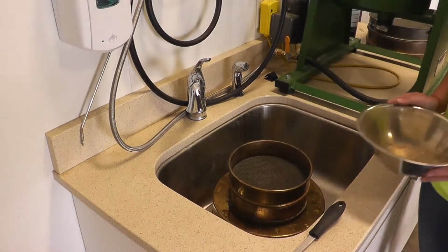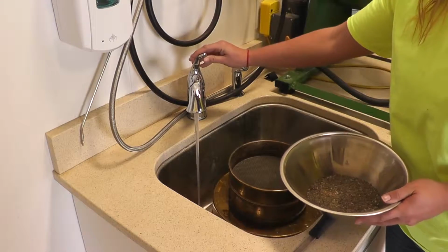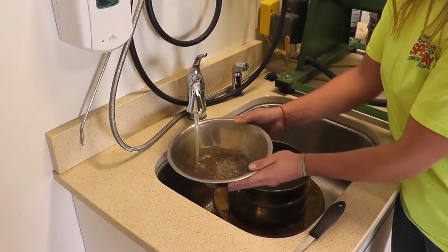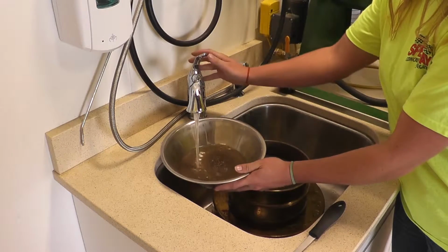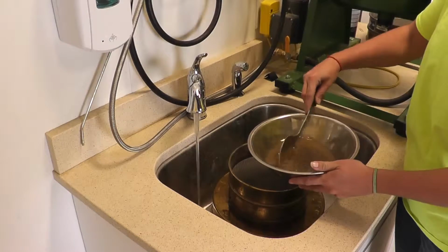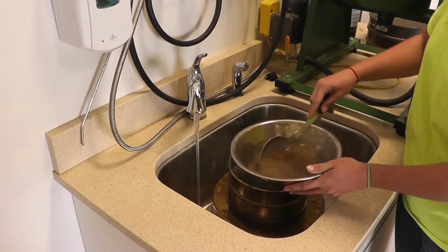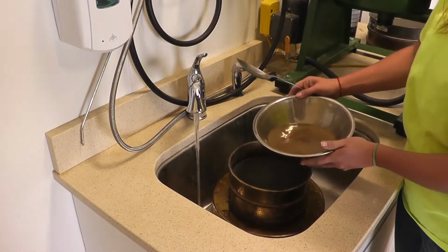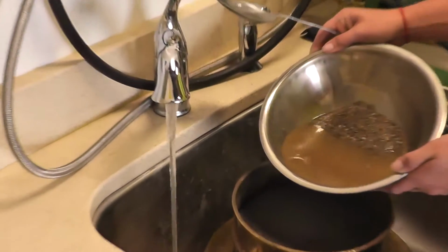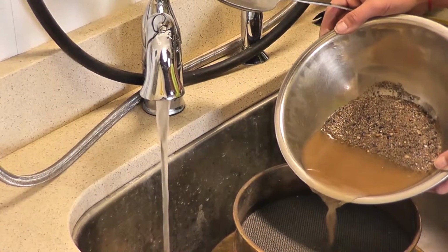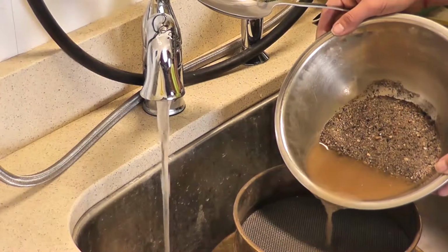For some specifications, an accurate determination of material finer than the number 200 sieve is required. Material finer than the number 200 sieve can be separated from larger particles much more efficiently and completely by wet sieving than through the use of dry sieving. Normally, this test is used on the test sample prior to dry sieving by AASHTO T11, and the total amount passing the number 200 sieve is the combination of the wet sieving and dry sieving processes.